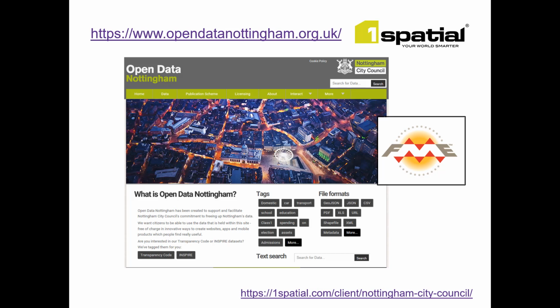So the guys in Nottingham have built some of these FME workspaces, these logical workflows, to pull together the latest data from different sources across the council, and then they publish their output to this website. It's pretty clever. They're using FME Desktop running on a Windows task scheduler, and that will run the process every night and then refresh the data daily. So it's all very hands-free, all automated, and up-to-date current data available every day.